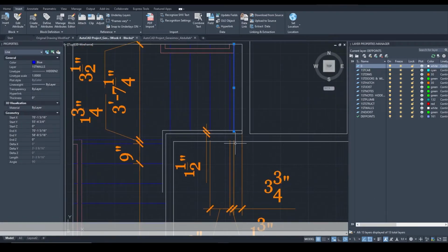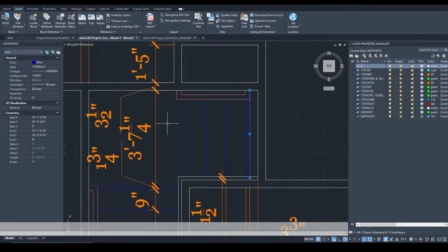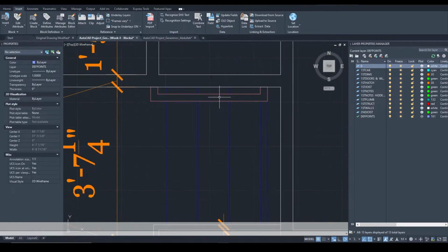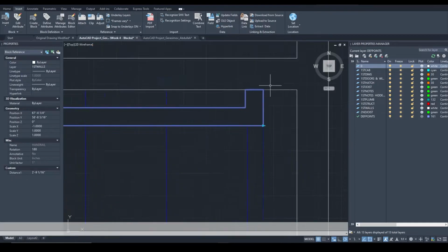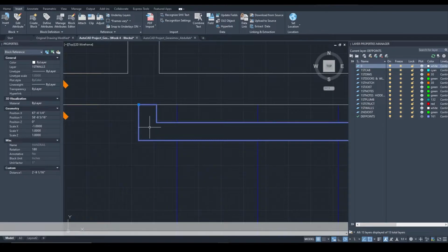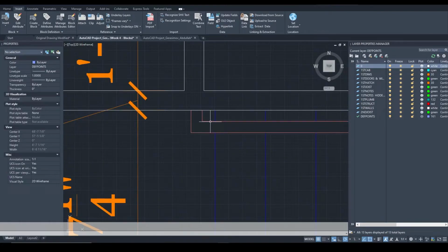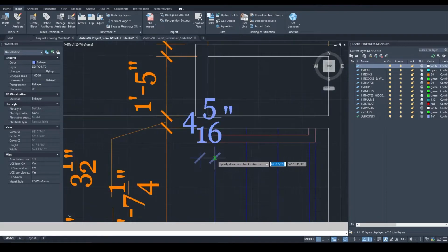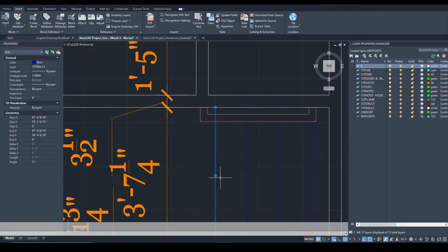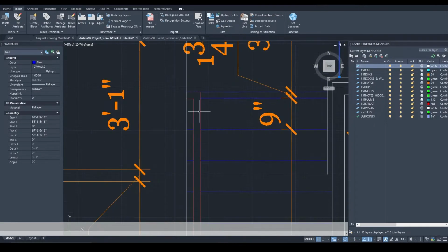Once you create these treads, go ahead and copy that handrail block, align the one portion of the block with the hidden line, and another one you can offset roughly. Again, it doesn't have to be precise, since in the field it won't be as precise, but you can say by 4 inches or 4.5 inches from this tread. Same goes here.